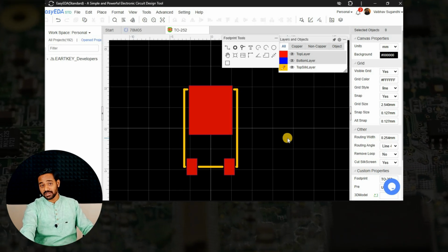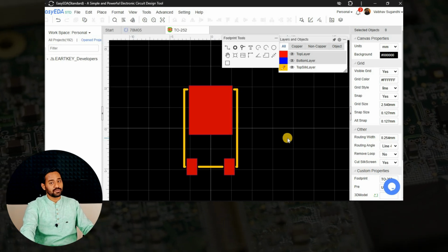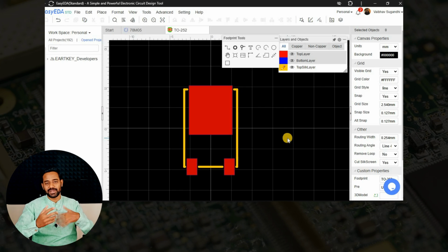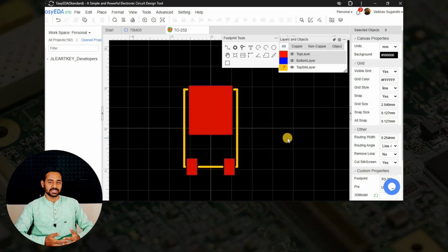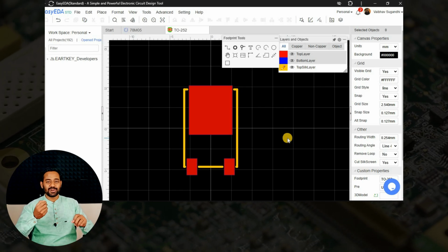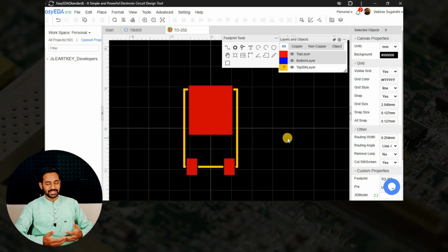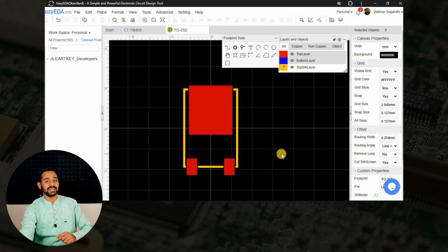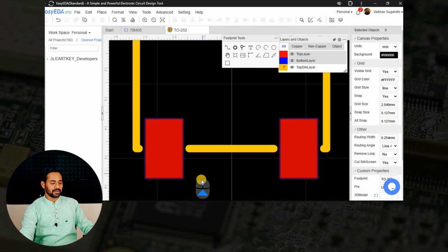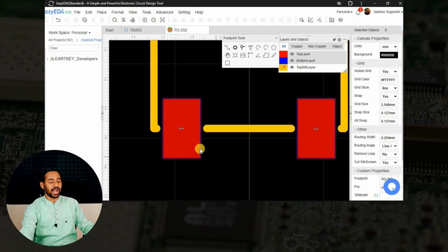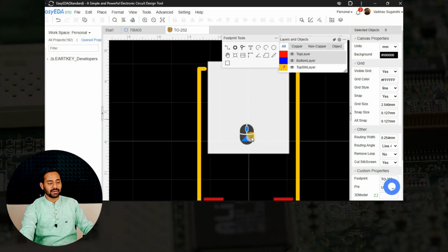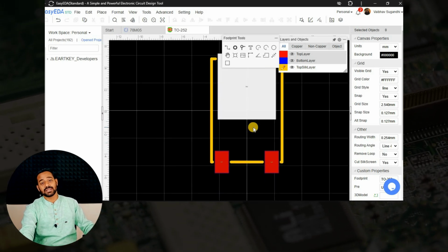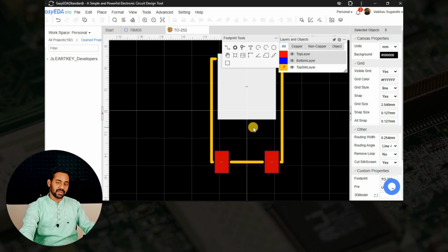Otherwise, it becomes difficult to adjust the component at the time of the soldering activity, because in a through-hole component we can bend the lead and make sure that they match with the soldering process. But in the SMD version, we cannot bend the lead however we want. So just make sure that you are matching the dimensions at the time of designing SMD packages. But also make sure that you have the pin numbers correct, because if you have a pin number wrong, you cannot change it once you are done with designing a PCB and fabricating it.